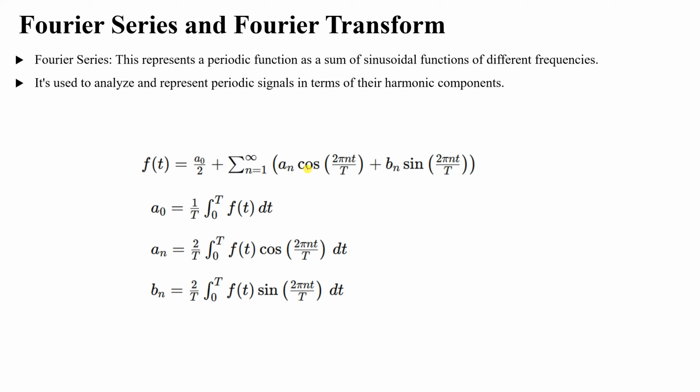So in order to design a filter that will eliminate these harmonics, we have to know what harmonics are even present in our signal. By knowing what harmonics are present and their magnitude, using Fourier series, we will be able to design a filter that kills the dominant harmonic. Okay, that is the whole purpose of Fourier series as one of the applications in electrical systems.